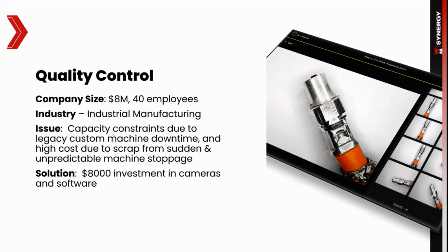So the root cause they found by going through some 5 why methodology was that some of the screws or bolts on the machine, when the machine hit a certain speed, would start backing out due to vibration. So there would be 2 cameras, one that would look at the side of it for the depth of the bolts to see if that's changing, and one that would look at it from straight on.